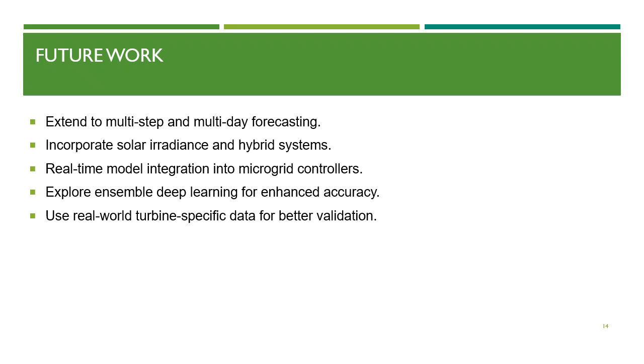For future research and work, several paths are promising. The model can be extended to multi-step forecasting, looking days ahead and not just hours, and having multiple layers of the LSTM models to enhance accuracy and reliability. You can also integrate solar irradiance and hybrid forecasting systems, which will improve robustness. Real-time deployment in microgrid control systems is also a key step that can be looked into.